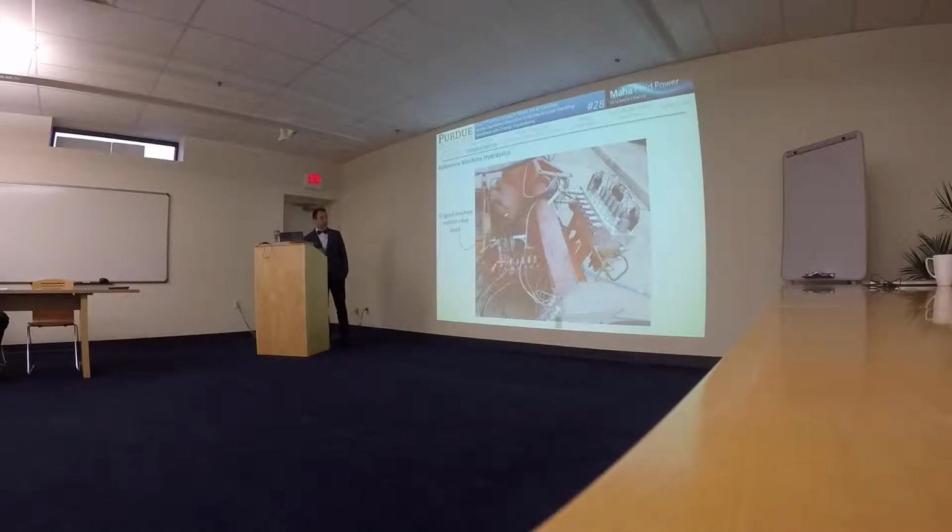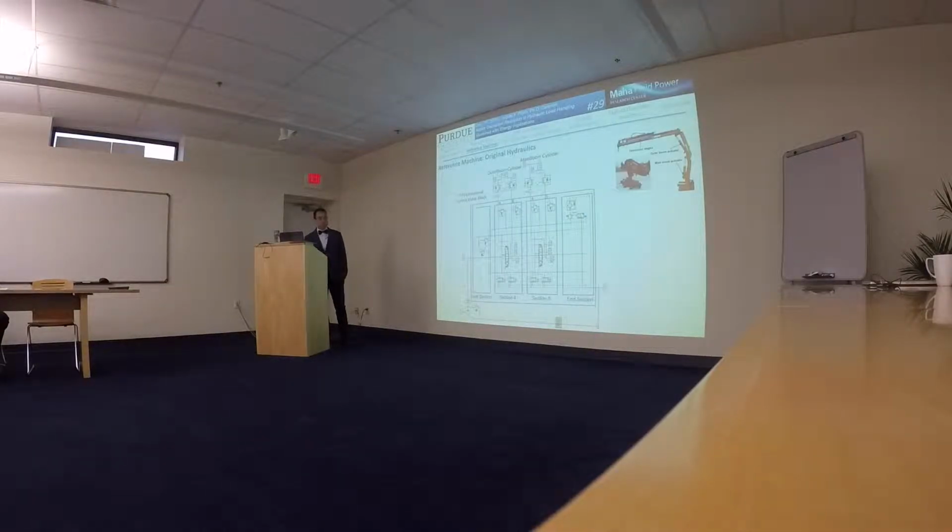The hydraulic system of the crane that you can see here has, in this close picture, the hydraulic system. So here is the original hydraulic system. And in order to show the flexibility of our controller strategy, we also equipped the machine with an alternate control block, which I will explain right in the next slide. So the original hydraulics of the machine, it's a fairly standard and simple hydraulics where we have open center valves. And so one peculiarity of this way of controlling this machine is that it's fairly simple, fairly straightforward, because we just need one input from the operator in order to control the motion of the machine, because now the 2 meter in and meter out edges are mechanically linked.